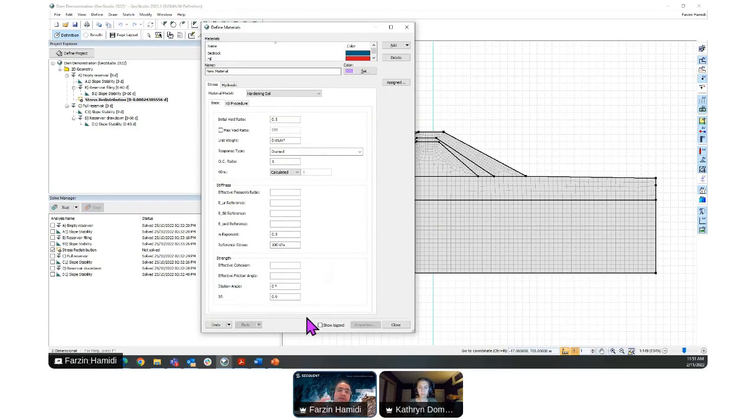Start with a simple analysis, for example in 2D with a smaller domain, doing a triaxial test and comparing it with a lab test result. Once you're happy with that, within a single project tree you can add extra geometry and run the model for the second geometry, this time in a more complex way.